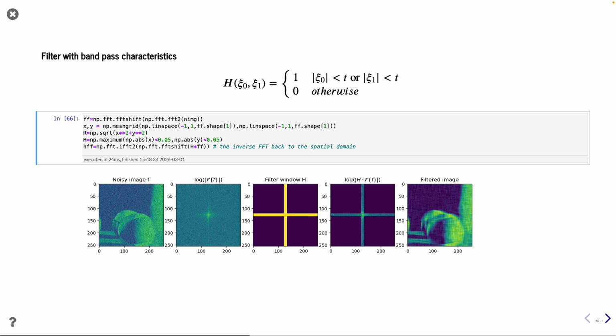So you can also play a little bit more with the filter kernels. You can do a bandpass characteristic, so you only want to focus on the low frequency parts around the axis in the two directions. And then you essentially start having an orientation sensitive filter. This example was just to play, and you will see that you have a lot of cross-like patterns in texture in this filtered figure. You get a strong low-pass filtering effect, but the cost is now that you distort your image.